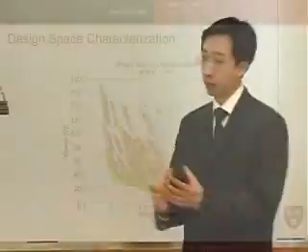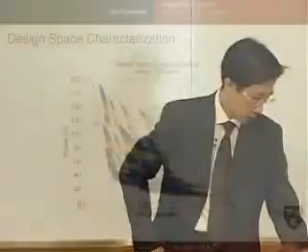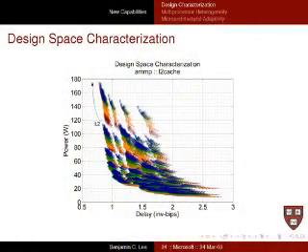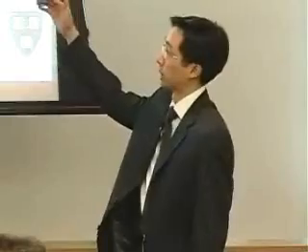The reservation stations have a really small impact compared to all the other parameters we considered. And the last parameter, level 2 cache: SPEC AMP is not memory bound, especially compared to other SPEC workloads. As a result, we see very little in terms of delay reductions, but we incur a significant power cost by increasing the L2 cache as we move from the small caches in the red to the larger caches in the blue.